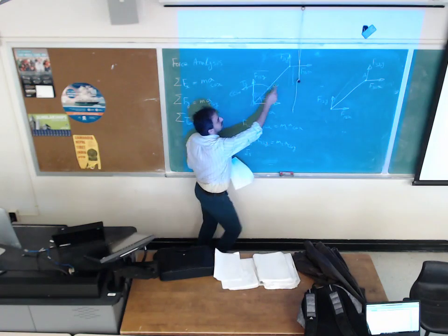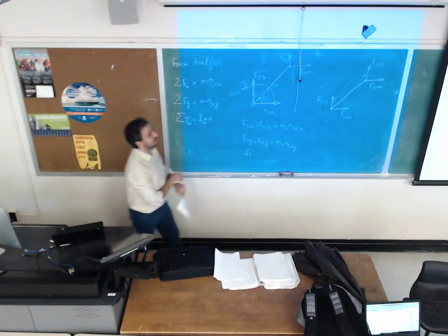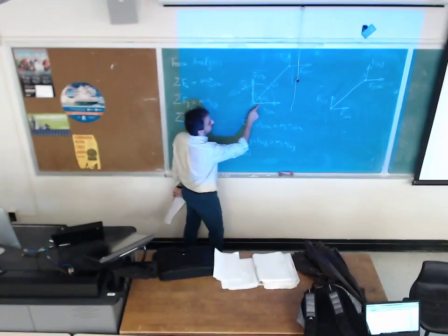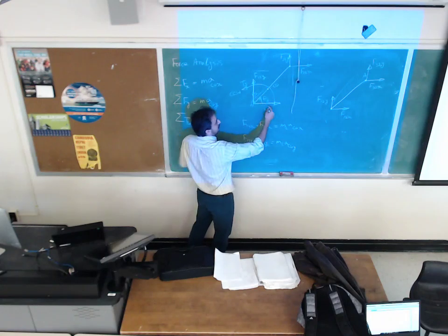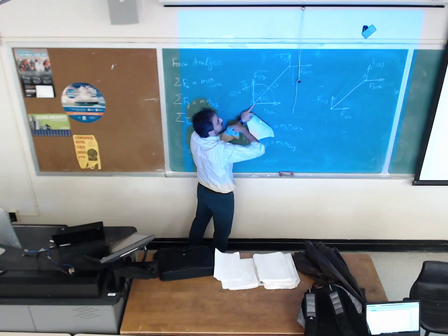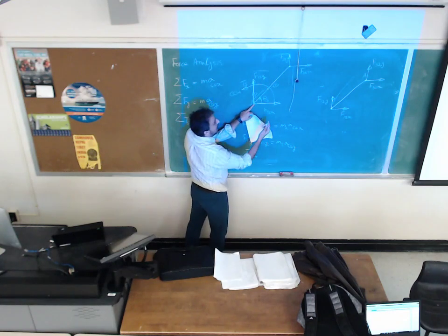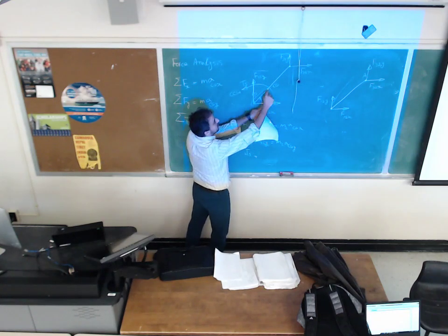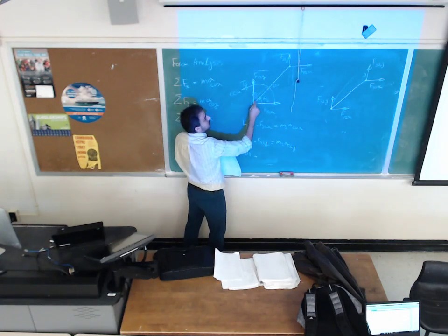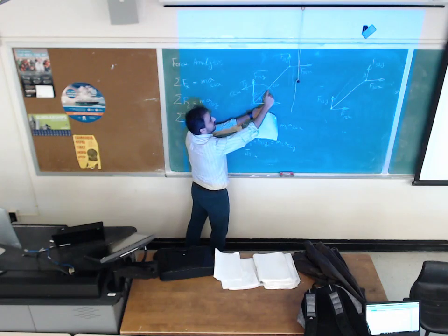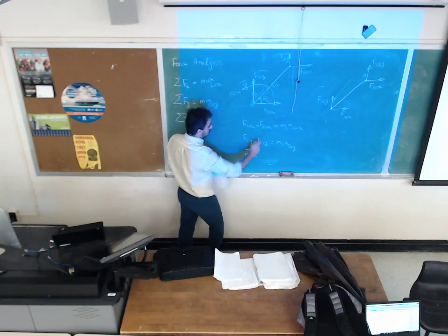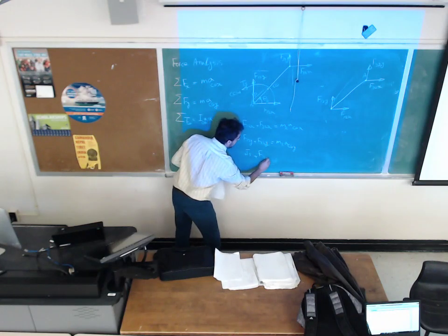So this force, you can imagine, is making counterclockwise rotation, so it should be positive. And how much would be the torque? This force times this distance. This guy is RG2. This distance is going to be RG2 sine of theta 2. So F12x times RG2 sine of theta 2 is going to give me the torque coming from this force.